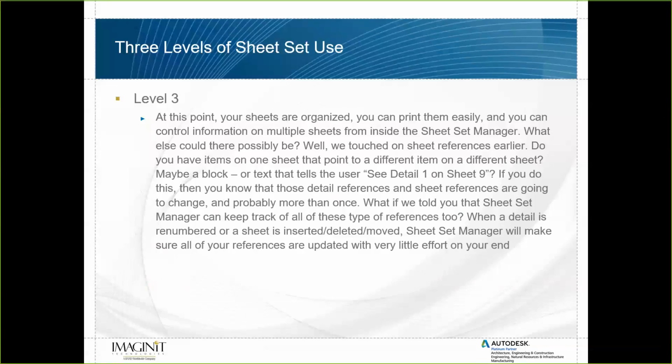And if we told you that we can manage this with the Sheet Set Manager, it can keep track of these references too. When a detail is renumbered or a sheet is inserted, deleted, moved, the Sheet Set Manager can actually help you make these changes to all those references with very little effort.